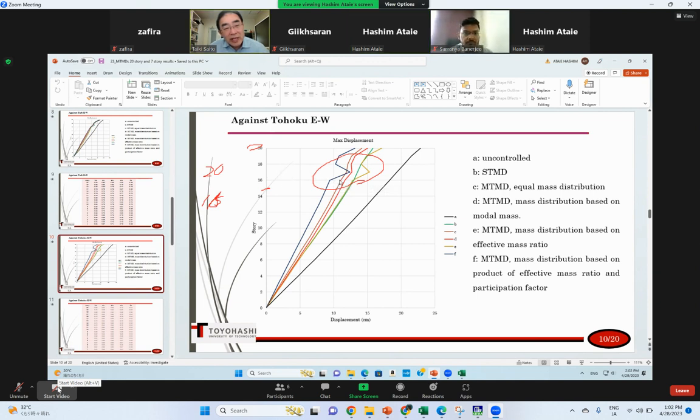So, but you have 3 TMD. Yes, it is 3 TMD. So 20, 15, and one more. Where? 20, 19, and 16. 19? Yes, it's almost equal to 20. Why is it so close? Because the largest amplitude of the second mode is also at 20. Because we already installed the TMD, we consider the second largest amplitude of the mode, which is 19.